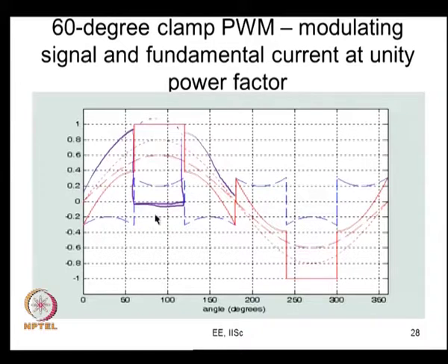So, you can use the same E on and E off, and here the energy loss is 0 because there is no switching, and you can calculate the average E on and E off, and you can multiply that by the number of switching cycles that it has effectively had, and you can find out how exactly the switching loss can be calculated, because the energy loss is known to you. You also know the switching frequency, how it is going to change here, except that you have got to account for this particular factor. Alright, so this is again the procedure. This is just a small modification in the way you calculate when you do a discontinuous PWM.